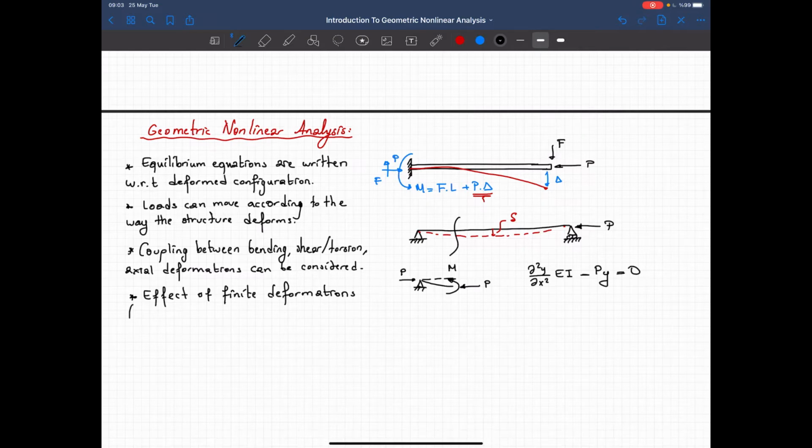So in terms of deformation, we can consider large strains. We can consider the change in length and or area in our strain definitions. Okay, if you do that, we are considering finite deformations. And instead of saying small deformation, we can consider finite displacements.